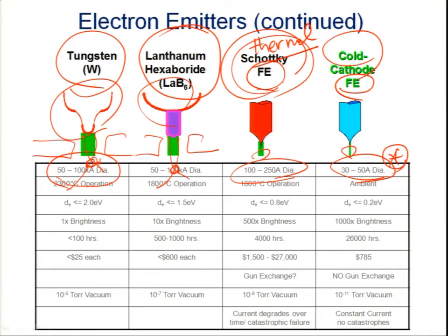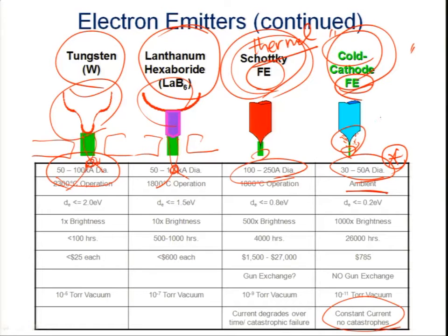As to the thermal field emission source and the cold emission source, since the cold emission source operates at room temperature, it needs maintenance, a regeneration process to remove the contaminants deposited on the tip, every 6 to 8 hours of operation.